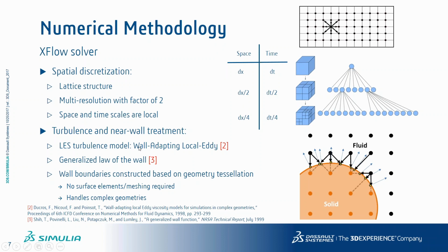And for the turbulence, we actually use an LES turbulence model, okay, which is a wall adapting local eddy model. LES is known to be a high fidelity model to describe turbulence because we resolve the turbulence spectra up to certain scales, and then for the smallest eddies, we don't resolve them anymore if we don't have a lattice size that is fine enough to discretize an eddy, for example. We will just apply an LES turbulence model in this case. So the LES turbulence model has a strong advantage with Lattice-Boltzmann of being very low cost compared to traditional methods.